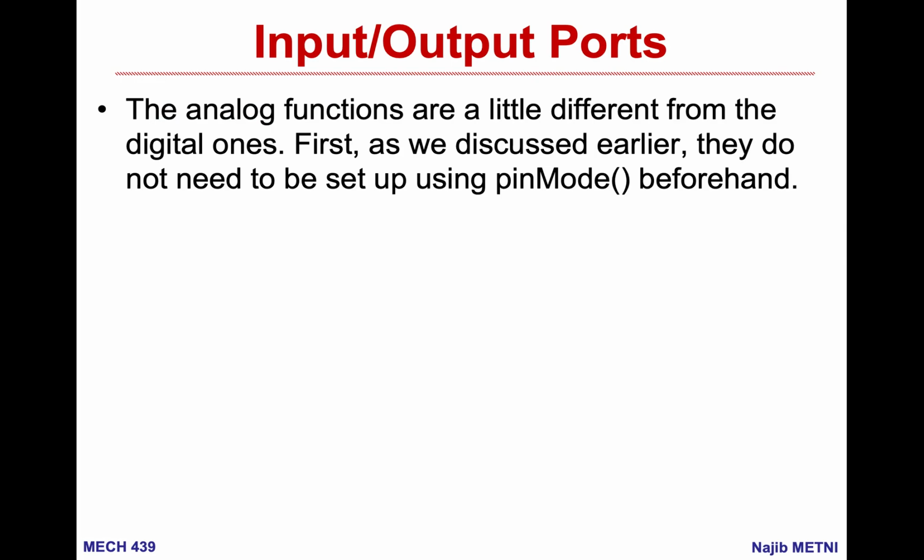We also have to understand that the resolution in this case is 5 volt minus 0 over 1023, being 2 to the K minus 1.